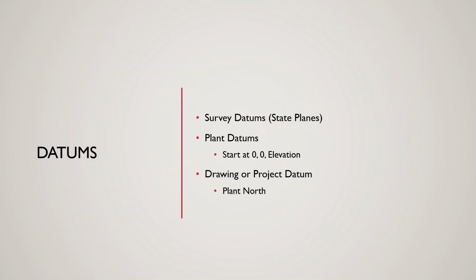When you put your point cloud together, you're going to have to move it in space to a location. And if you use the state plane as your location, when you bring your point cloud up, it will come up exactly as it is in real life. The downside of going to state planes are AutoCAD in particular. There may be some other software that handles state plane really well. AutoCAD does